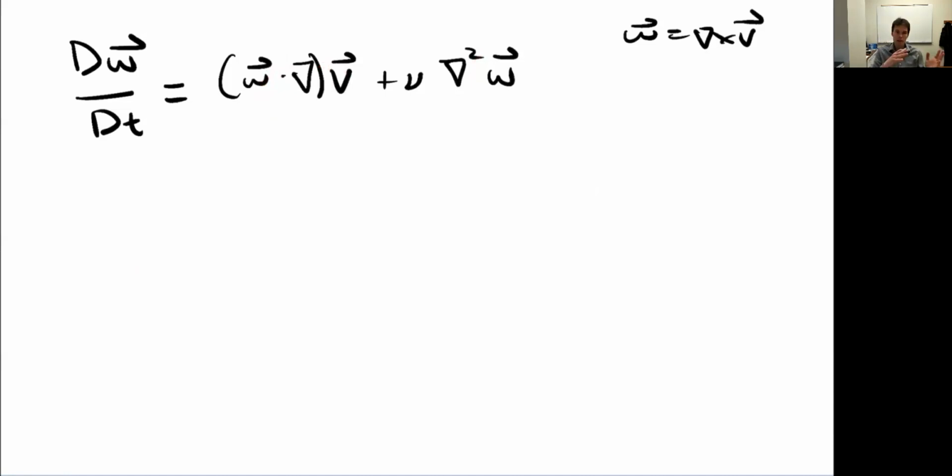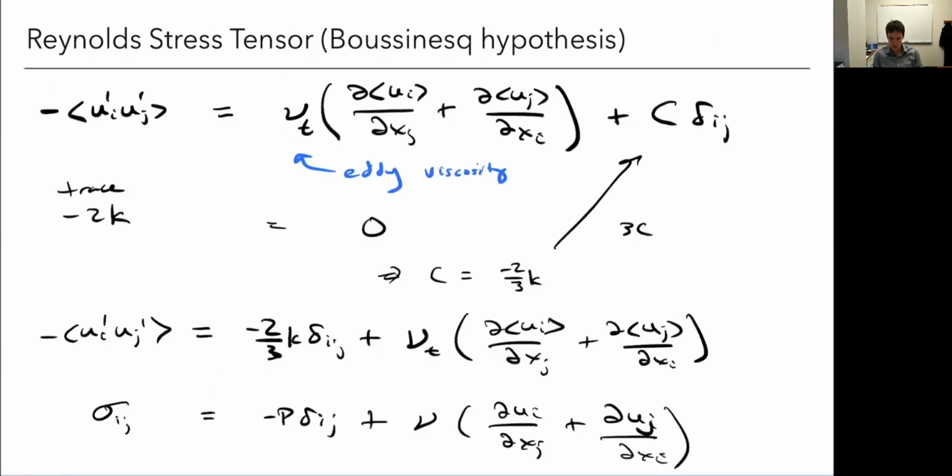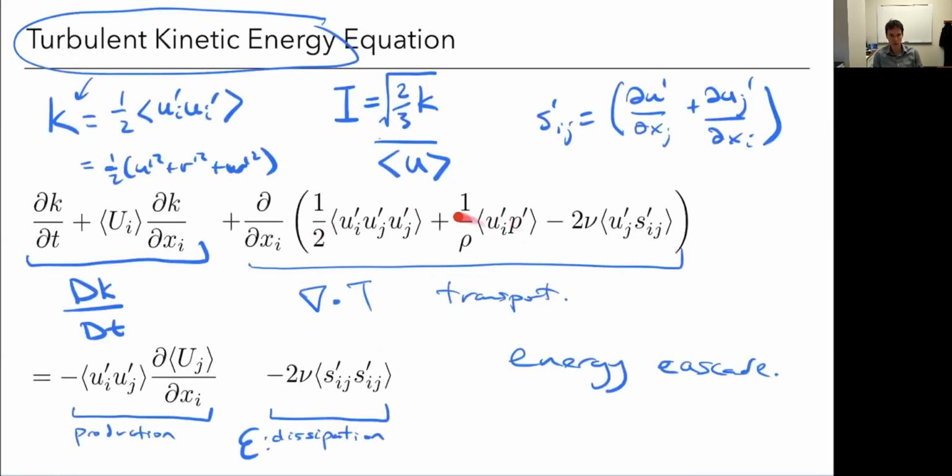So it kind of stretches and tilts the vorticity vector. And this stretching, although it may not be obvious unless you write this out, only occurs in 3 dimensions. So if I have a 2-dimensional flow, this term is always 0. But in 3D, this is what causes vortex stretching. And that stretching is essential for this kind of energy transport, this transfer of energy on the different scales.